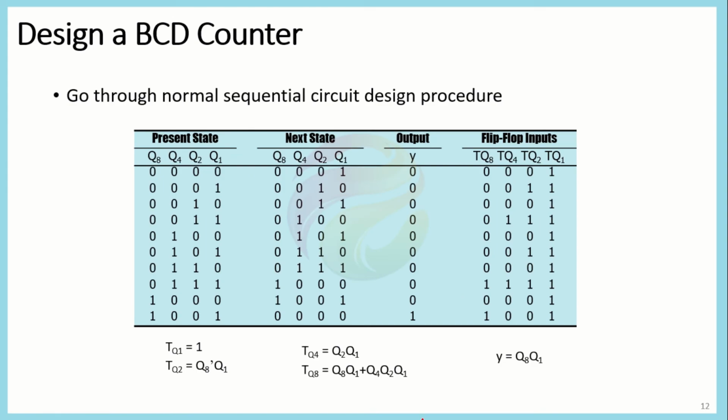Now we would see the design of a BCD counter. Previously we have discussed it using the asynchronous module, or the ripple BCD counter. Now we will be discussing a BCD counter using the standard sequential design, in which all the flip-flops are connected to a single clock.